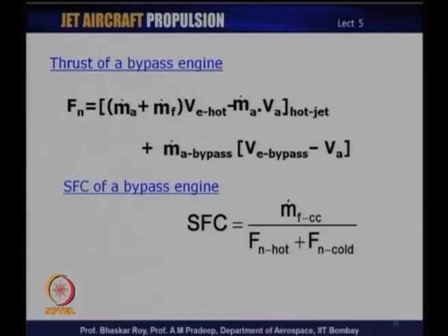The SFC of such an engine is simply referred to in terms of the mass flow that is pumped into the combustion chamber divided by the total thrust that is being produced, the combination of hot thrust and the cold thrust, and that total together gives you the SFC. And now, one can realize, looking at this figure, why there is a huge SFC benefit when you use a bypass engine, and we will of course be talking about this benefit of SFC of bypass engines more and more.